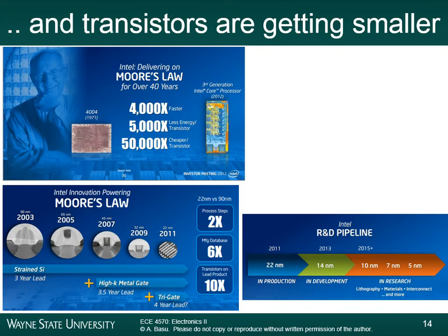that metals have this ductile nature, ductile and malleable. In order for a material to be malleable, the crystal structure has to change, right? Because the atomic structure has to change when you bend the material. So the way that metals do it, they're not quite amorphous. They're actually not quite crystalline either. They're polycrystalline. What happens is that in metals you have those regions of crystallinity, and when you bend the metal, those regions of crystallinity actually slide up against each other.